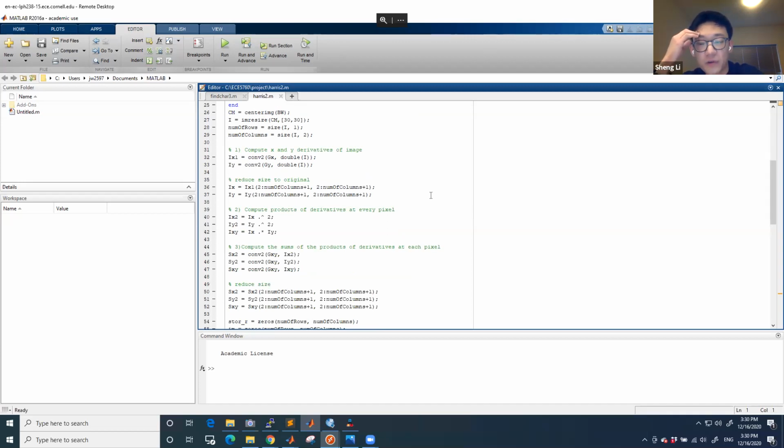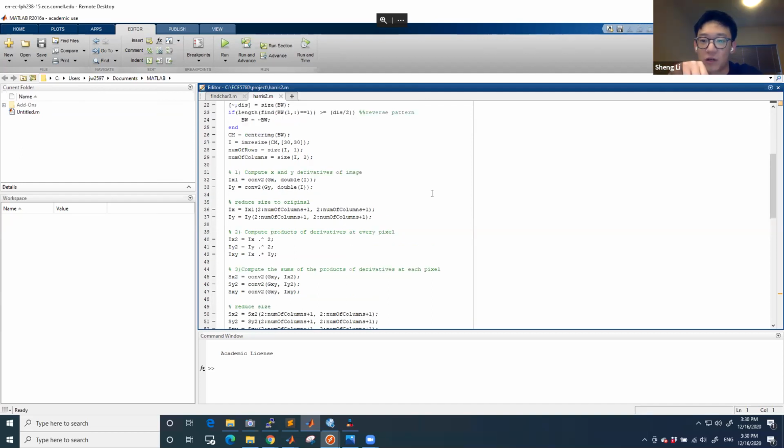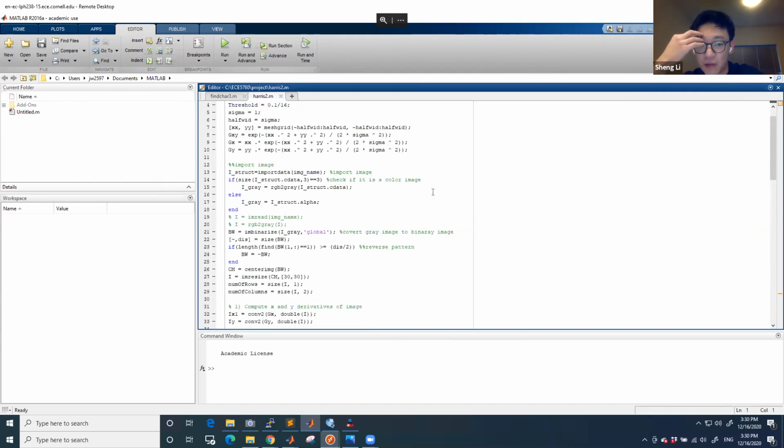It is always a good idea to pre-process the image first with a filter to filter out the noise. We do that with a Gaussian filter. The reason is that Gaussian is linear separable. So if we use a Gaussian filter first, then do the spatial derivative, we can just do convolutions. So the calculations working on the FPGA can be much easier. We can just use the FPGA to do a bunch of convolutions.